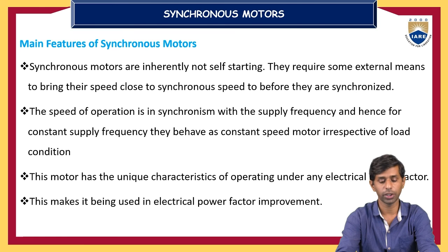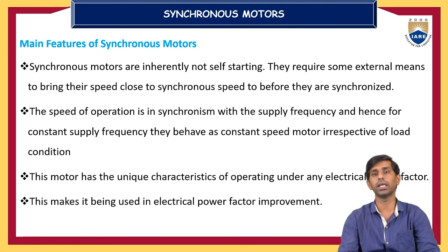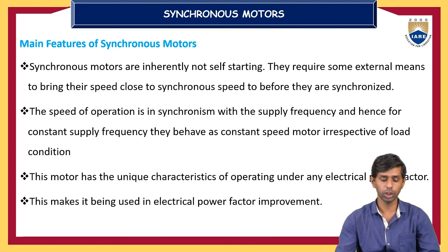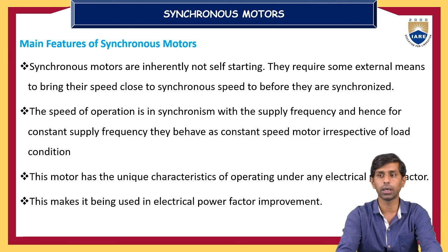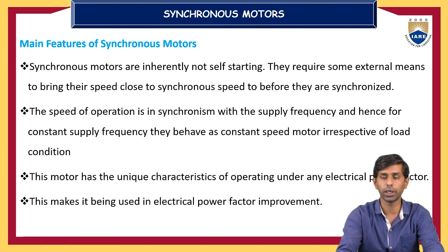The speed of operation is in synchronism with the supply frequency, and hence for constant supply frequency, it behaves as a constant speed motor. So the synchronous motor runs at constant speed, equal to the rotating magnetic field, irrespective of the load condition. Whether you are increasing or decreasing the load, the speed of the synchronous motor will not change.